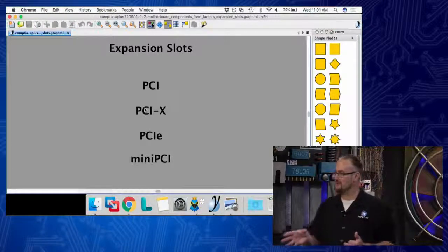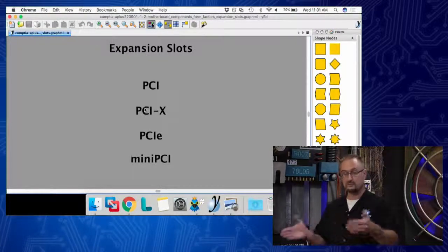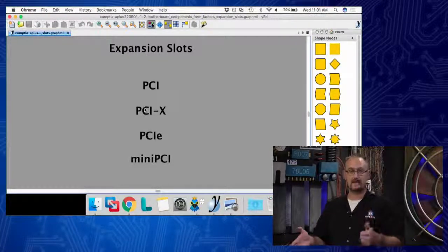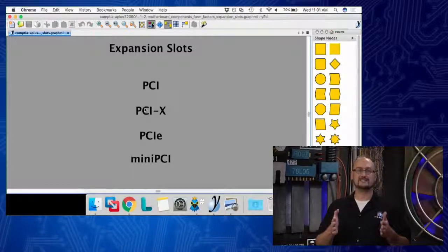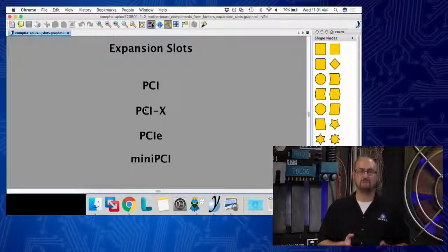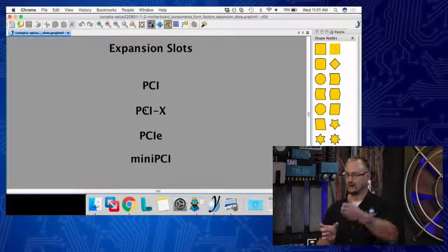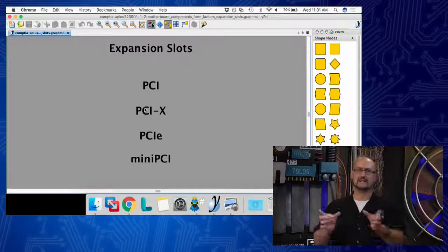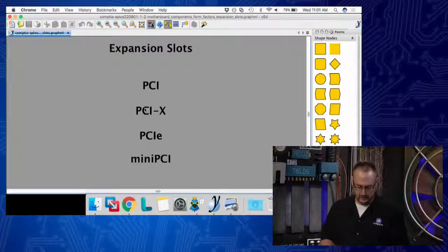So you can get a total, believe it or not, maximum the standard supports, of 10 PCI cards, if your board supported it. And I want you to remember the bits, right? It's the width of those traces, that pathway that we talked about that goes into the CPU. It's 32 bits. Overall, it's really 64 bits, but there's kind of like a dividing line between the two 32 bits, and each of the 5 cards sits on its own 32-bit bus.